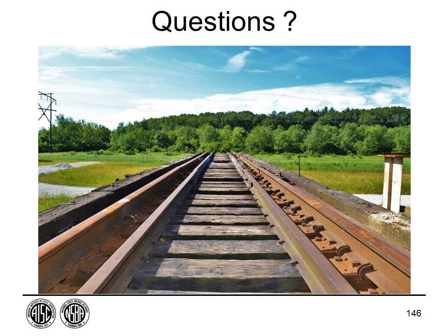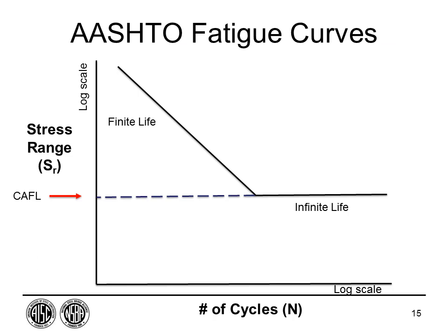And our first question, I will take us to slide 15. I think this is where it first came up. Could you remind us, what does CAFL stand for? Sure. It is constant amplitude fatigue limit. And so that simply is saying that if my fatigue stresses, let me grab my pointer back, if my fatigue stresses are below that value, so down here, I would be expected to have infinite life in my detail.